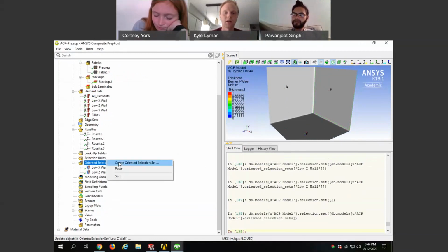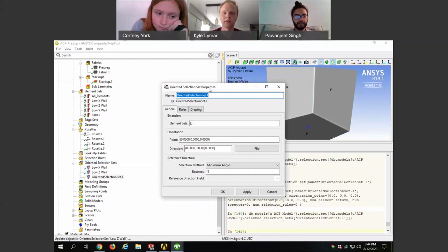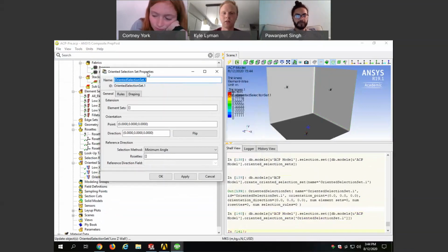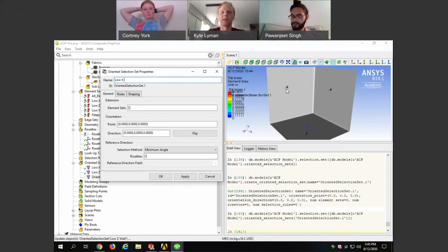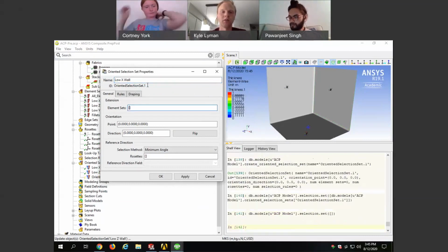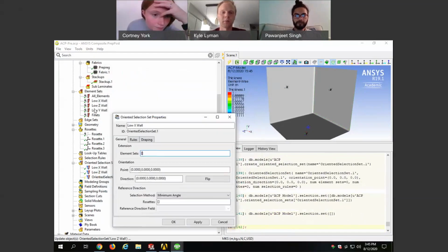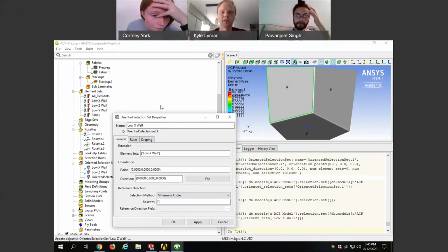Luckily, a wall is a pretty simple shape to make. It'll just be a flat plate, so should I be able to start that with a shell as well? Correct. Start with a shell, then define the thickness later. Like how we provided a dummy thickness earlier, you'll have to do that as well. I'll show you how this thickness is actually assigned in a little bit.